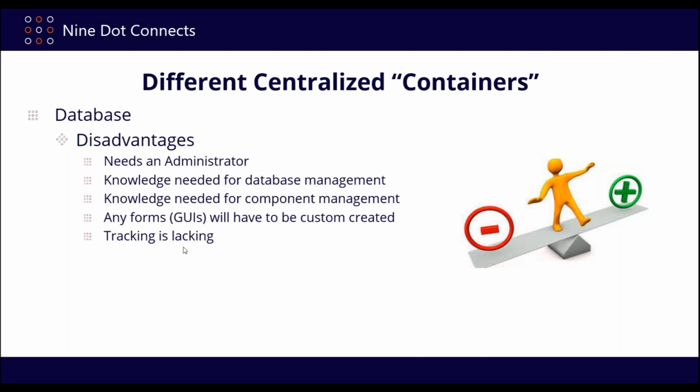The larger ones can do it. The more simplified ones really aren't going to track a whole record of who's made what change where. And then of course you've always got your graphics need to be synced with the database. So it goes back to what I said earlier. You've got your symbols, you got your footprints, and now we've got to make sure that our database knows where that symbol and footprint library is residing within our system.